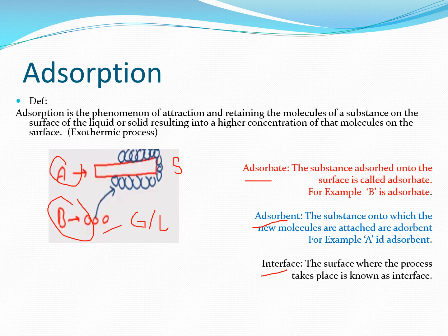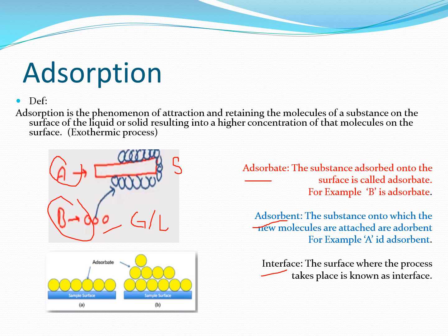A little bit about the last concept: we have physical adsorption and chemical adsorption. This is a physical adsorption in which the molecules of B are retained on the surface of A and are captured there through weak van der Waals forces, and they can be removed again by regenerating the column through steam. Another concept we discussed was the simple surface, multi-layer and unimolecular layer adsorption. Mostly unilayer is in chemical adsorption and multi-layer is for physical adsorption.